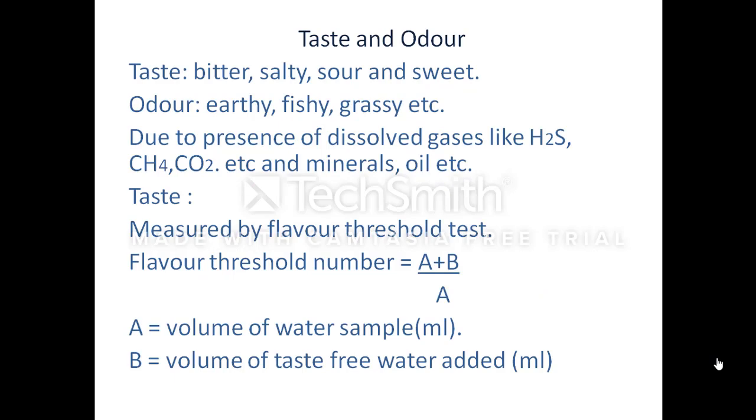Taste and odor. The taste can be bitter, sour, salty, or sweet, and the odor can be earthy, fishy, grassy, etc. The taste and odor in water is due to the presence of dissolved gases like hydrogen sulfide, methane, carbon dioxide, and minerals, oil, grease, etc.